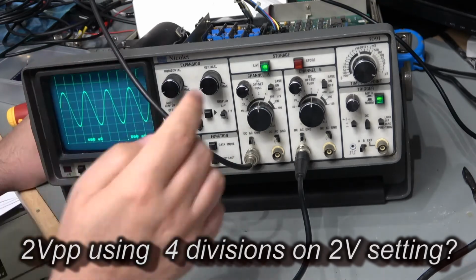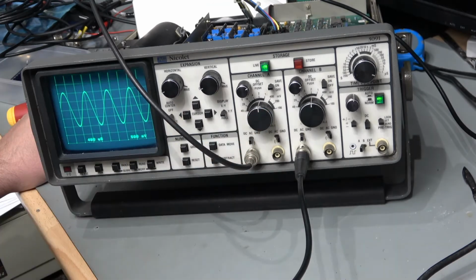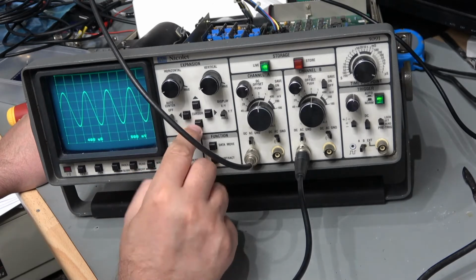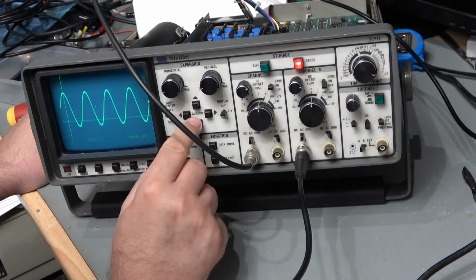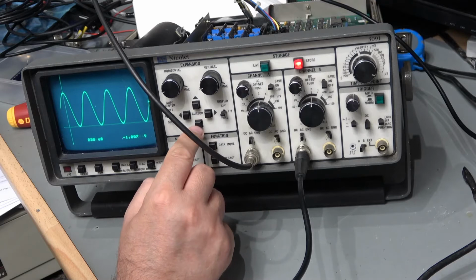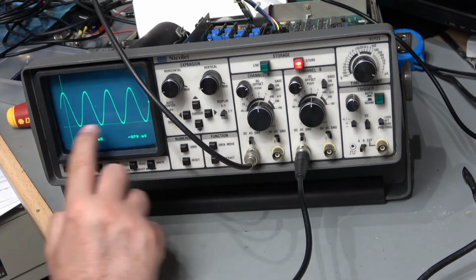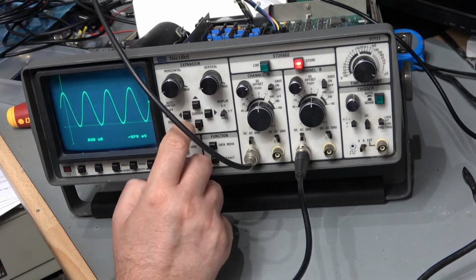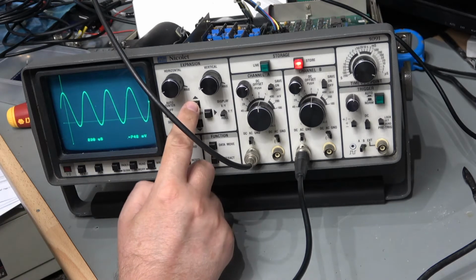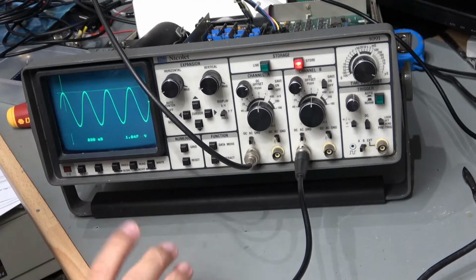So this is all down to the analog digital conversion. So it's saying it can sample up to plus minus 2 volts, which will be a range of 4 volts in total. Blinking heck. So if I store that, well, yeah, I can actually move around 2 cursors now. The grid is turned off. And we can find at the bottom there, as close as possible to minus 979 millivolts, or possibly a bit higher. Yeah, it's about minus 1 volt. Let's move up to the top. Yeah, and about plus 1 volt. So plus minus 1 volt, absolutely spot on.